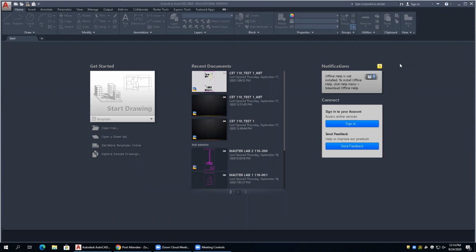So properties such as color, line type, line weight, visibility. We can turn things on or off. And they also use another state of visibility called freezing and thawing. So we're going to look at those. We can also tell it to plot certain layers and not other layers. So for people that utilize AutoCAD at a high level, layers is the name of the game. Everything you're doing is layer based.